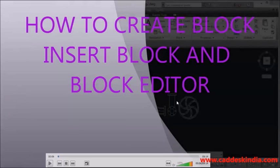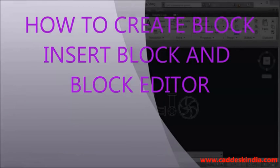Today we are going to learn how to make a block, how to insert a block, and the block editor. Before starting the video, let me tell you what a block is. A block can be defined as a collection of objects that are combined into a single named object, which means if you want to insert multiple objects at a time or make multiple objects a single selected entity, then you have to make a block out of them. So let's start, guys: how to make a block.